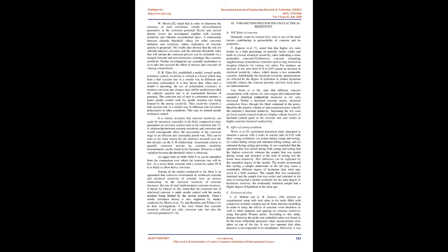A. W/C ratio of concrete. Generally, the water to cement (W/C) ratio is one of the main factors contributing to the permeability of concrete and its properties. T. Rupnow et al. [7] stated that a higher W/C ratio results in a high percentage of porosity, more voids, and leads to a lower electrical resistivity value, indicating a more permeable concrete [31].